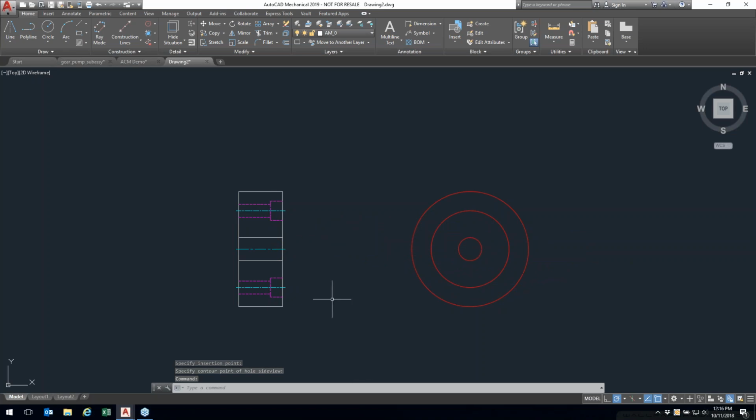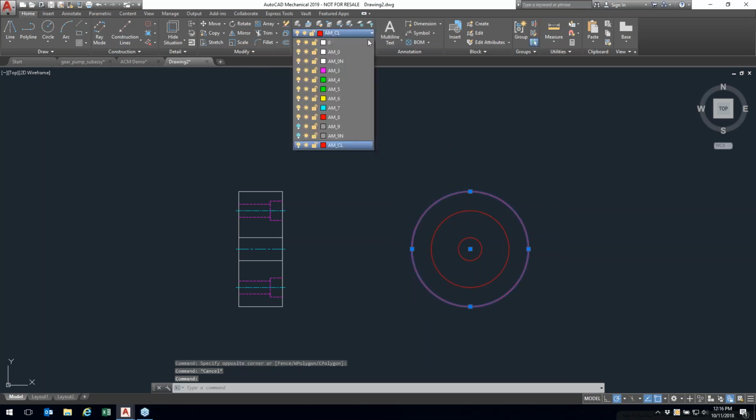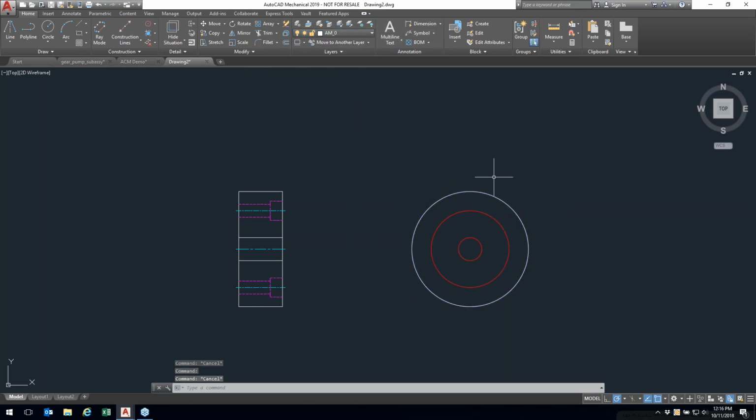So now in this case, I've got essentially things like this is my center line, that's my internal edge, that's my external edge. And what that trace contour does is I can select that and then select locations or objects inside the zone, and it will in turn fill them in. Obviously, I can also grab these elements. They're nothing special. They're not unique object types by any means. So all I would have to do in this case is just move them to the correct layering in order to convert them to complete objects or real objects inside of the space.